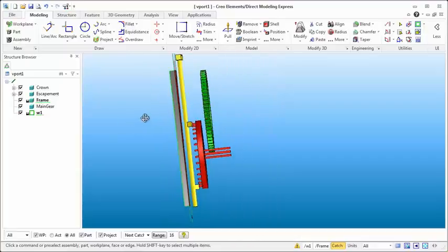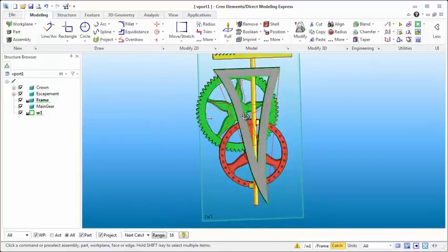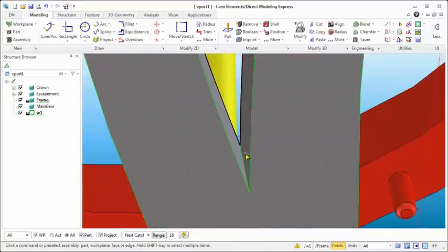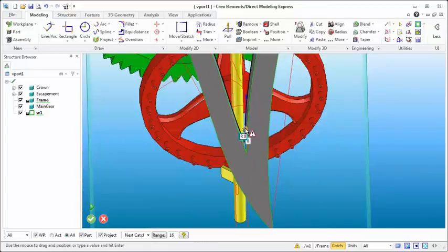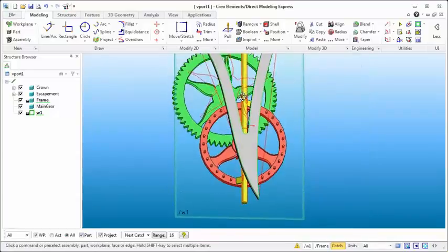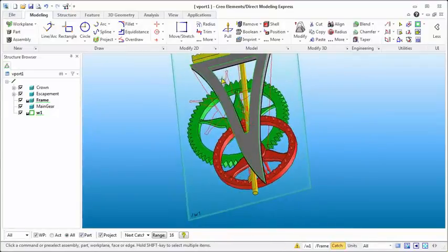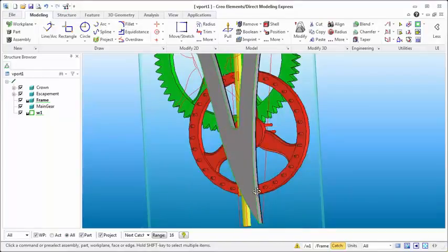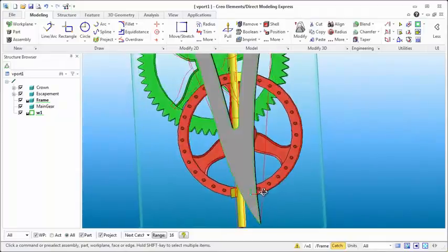So now we've got that frame element that's kind of sticking out a little bit. It's pretty curvy, but we still need to do a couple of things. First thing that I was mentioning before is that I'm not very happy with how that works out there. So let's just put a radius in there of 4, and that looks pretty good. So now that we have that radius, we might want to consider putting radii on some of these others. I'm not too convinced that it would be totally necessary.